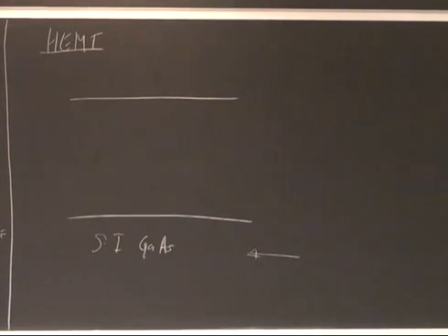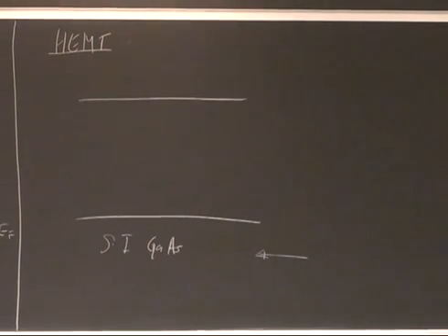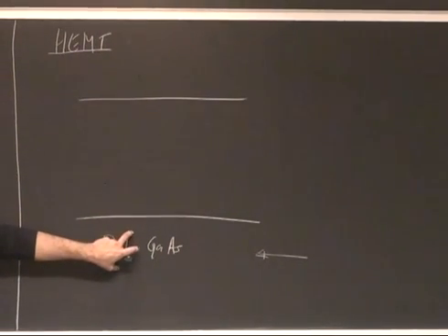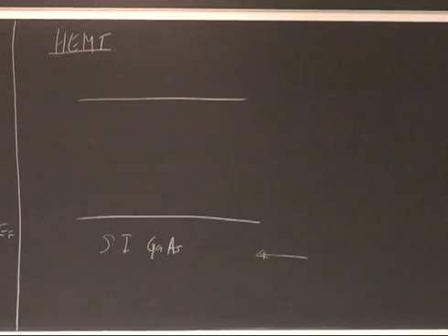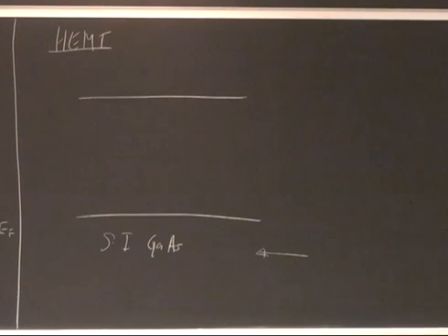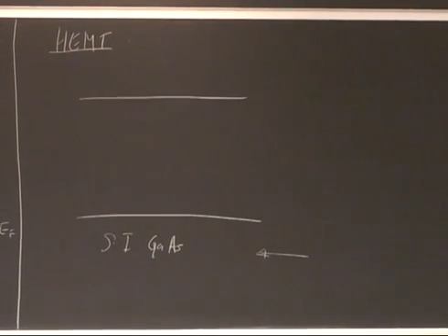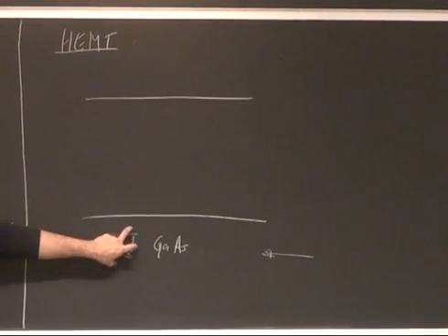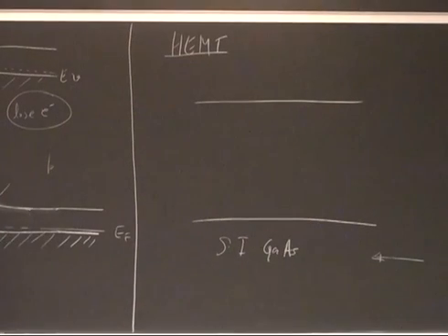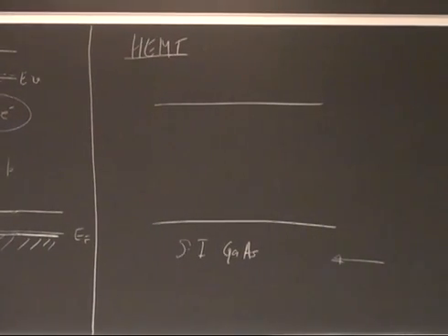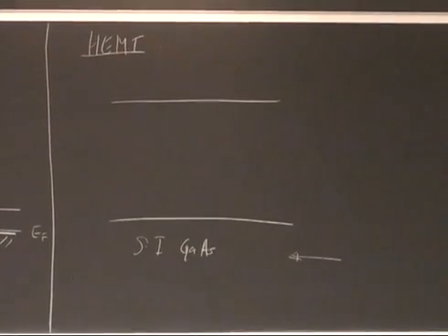Most compound semiconductors that are used for electronics in any way, be it high-speed electronics or high voltage, need a layer which is highly insulating. In fact, if you are doing field effect transistors, it is actually not very difficult to make a semiconductor layer conductive. But it is very difficult to make it insulating.